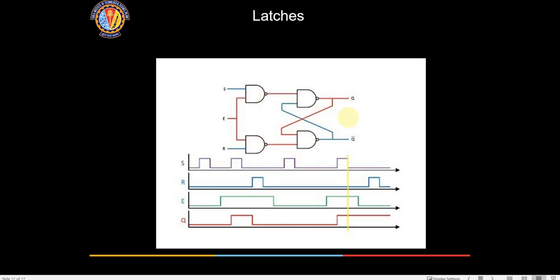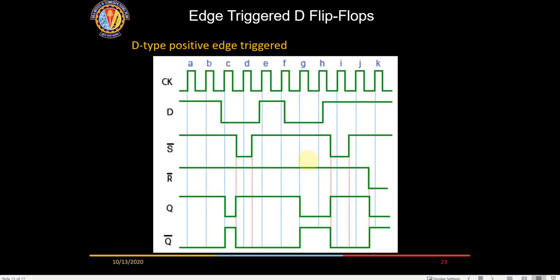Yeah, the functioning of the latch has to be extremely important, right? There will be some hand-drawn graphs also, so you'll have to know that set means it is setting the output to 1, reset means it is resetting it to 0, right? And a few students asked me a doubt on the D flip-flop. See, reset and set override the clock and data, right?